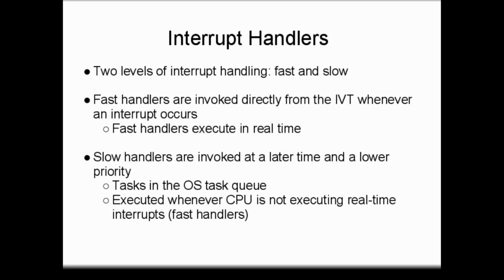If any large-scale data transfer needs to occur, say we need to get a lot of data from the device all at once, this operation is handled by having the fast interrupt handler enqueue something called a task into the operating system's task queue.